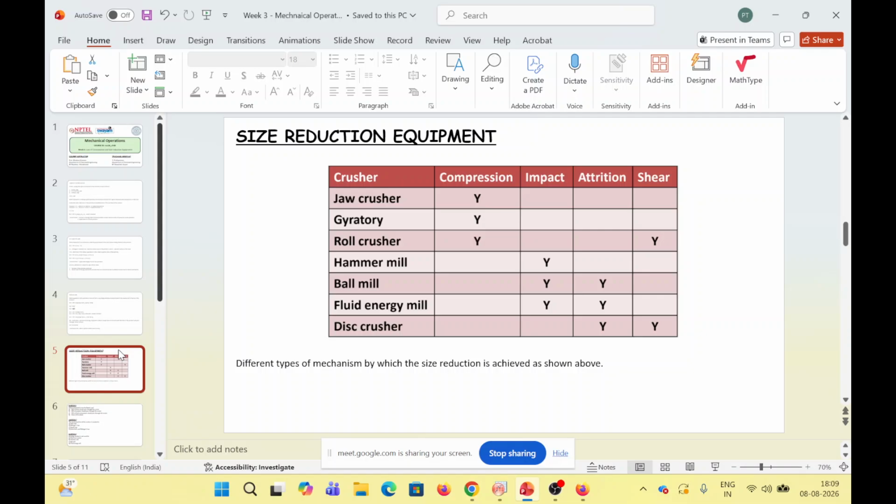more number of balls, or you can say high ball density. I mean the grinding media that you are going to use, the steel balls, they need to be highly dense, or you need to provide a longer residence time, or you need to use finer balls.